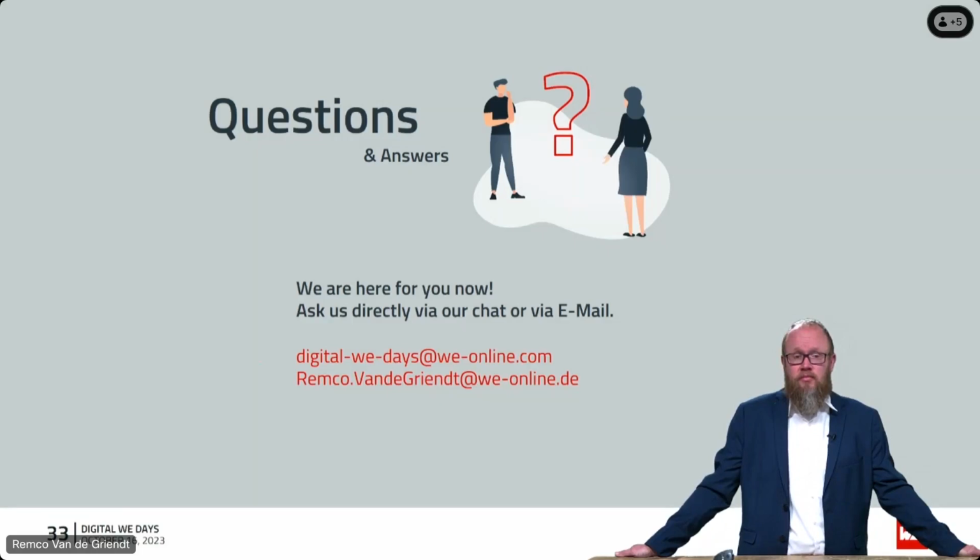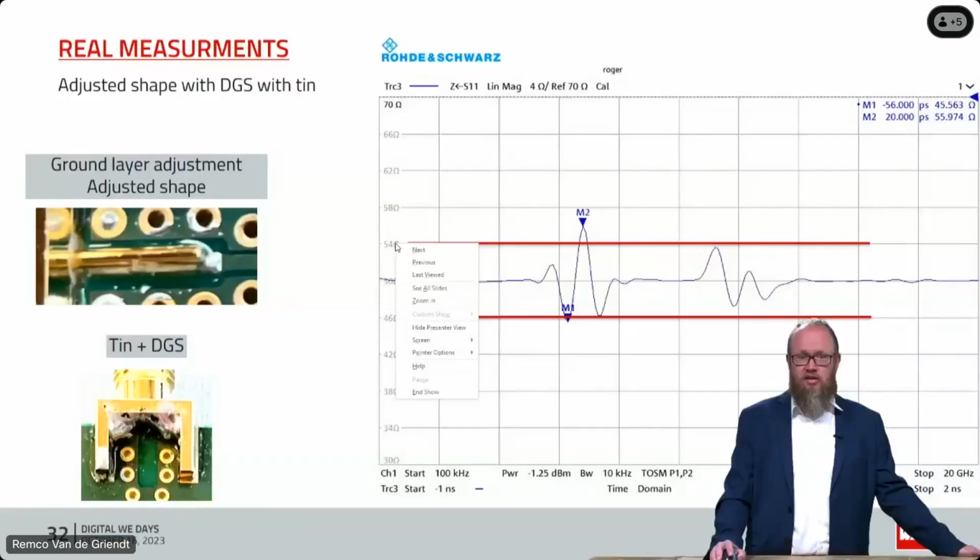Thank you. Next question: why isn't the signal pin of the connector soldered beginning from the edge of the PCB, where the pin's pad starts, on the first picture especially? You have here a mismatch of the impedance. I have a look at it that way, the bridge made by the pin.